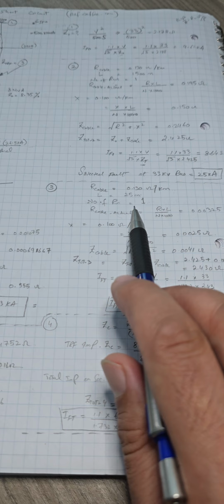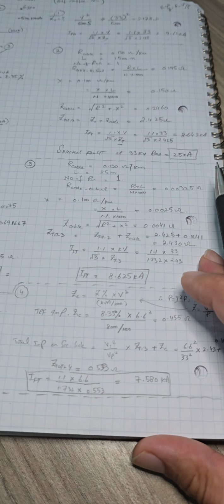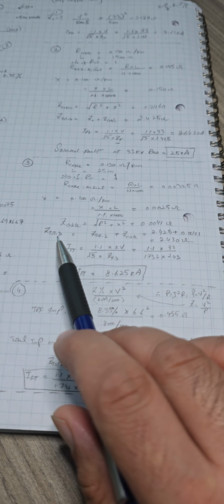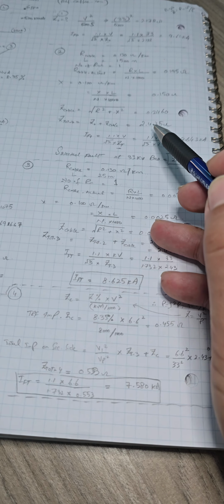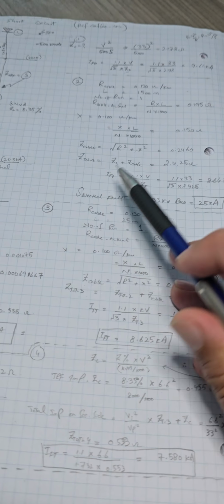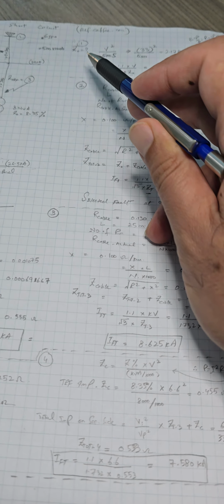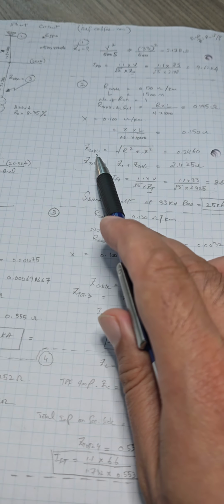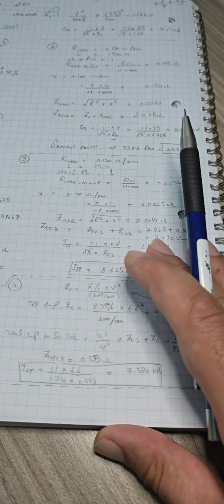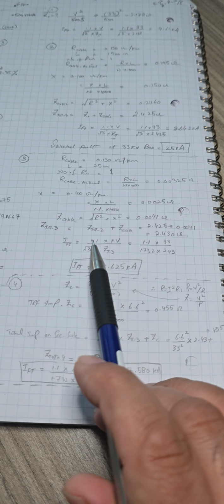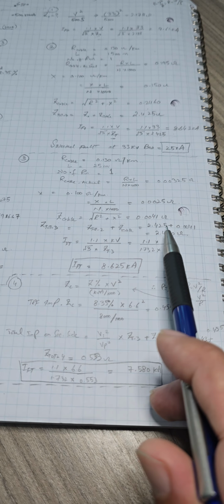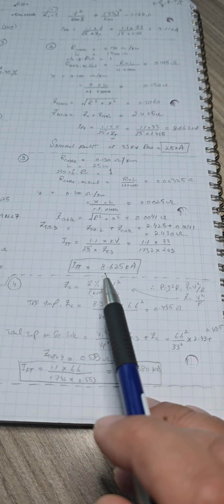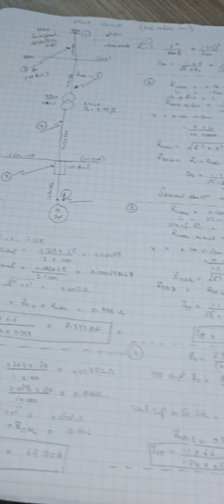Then we have the number of runs, the resistance of the cable, the reactance, and finding the Z cable, and then Z total. In this case, Z total would be this one plus this one. So what I did, I just made it Z total 2. Z total 2 is the summation of Z cable plus Z naught. For simplicity, I take Z total plus Z cable, and the value would be this one. You just have to put the value here, Z total 3, and you will get a short circuit of 8.62 kiloamps